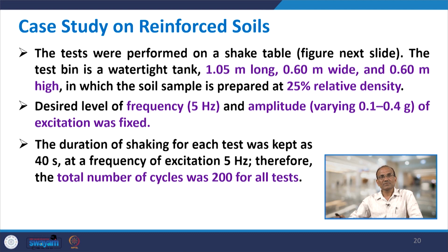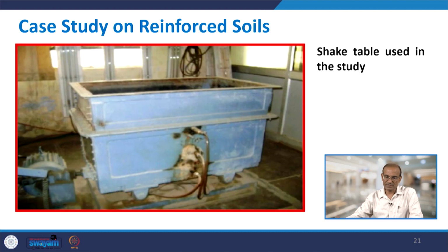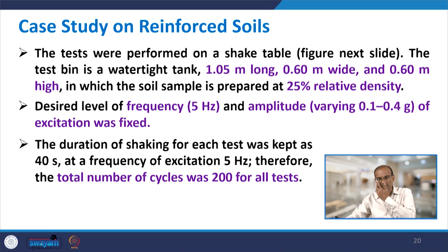The tests were performed on a shake table, shown here. This is basically a watertight tank. The length of the tank is 1.05 meter, the width is 0.6 meter and the height is 0.60 meter, in which the soil sample is prepared at 25% relative density. So, the relative density of the Solani sand used inside this shake table is 25%.